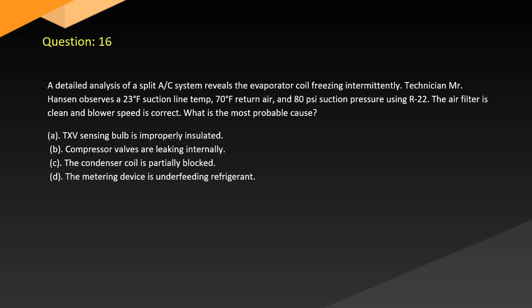A. TXV sensing bulb is improperly insulated. B. Compressor valves are leaking internally. C. The condenser coil is partially blocked. D. A metering device is underfeeding refrigerant.